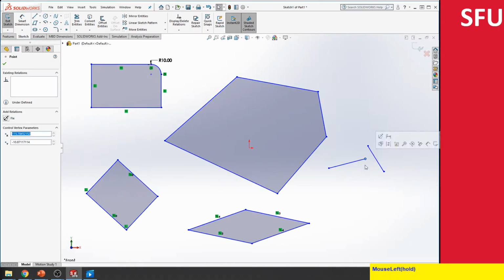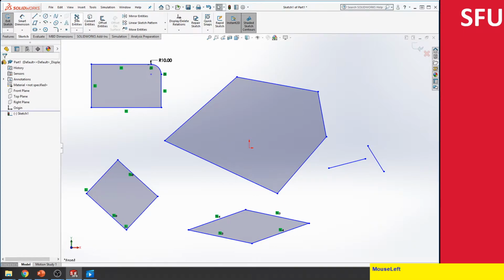So in case you didn't want to do that, what I can do is click on this trim extend option. You can either trim the entity or extend it. Let's do extend first because my line happens to be shorter. Notice that as soon as I click on it, it gives me an orange guide saying that I want to take this line all the way to the other line. So I'll do that and then it extends it.